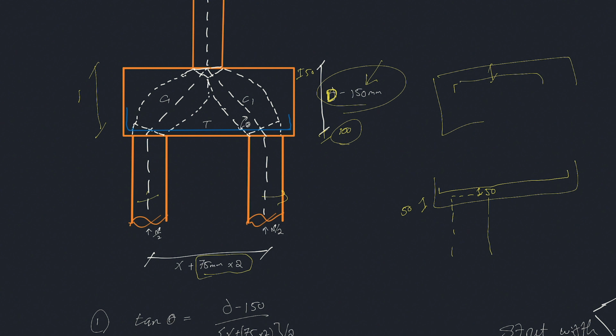And as you can see here from this 3D sketch, basically your column develops a little bit of its forces, about 50 to 100 mil into the concrete, and then it starts splitting them into one strut here and one strut there. And basically this area that is shaded over here, that is the size of one strut, and this is basically the size of the other strut. And usually your circular area of the pile is much bigger than the area over here. Yes, the areas don't match.